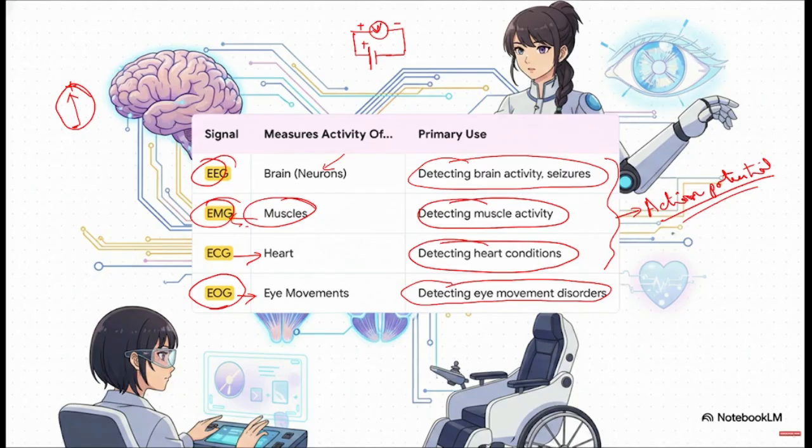They will be having two terminals, one positive and one reference electrode, which in general terms we call the negative electrode. But it is regarded as the reference electrode. Now we are having two sets of biopotential amplifier, one for the orbital electrodes and one for the canthi electrodes, and then outputs from those are being taken, and then you have to multiplex the signal.